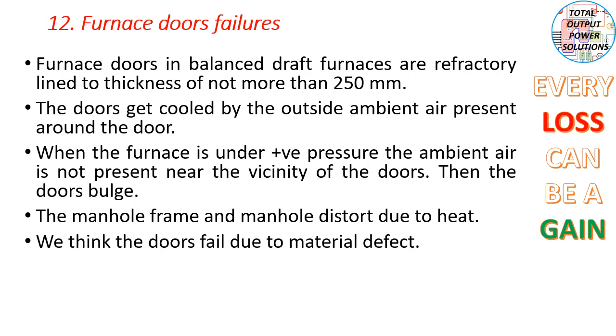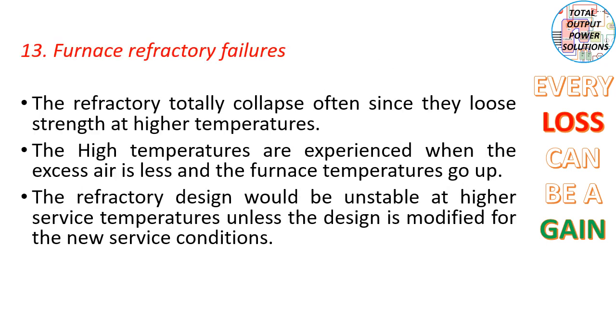Then furnace door failure. Furnace doors in balanced draft furnaces are refractory lined to a thickness of not more than 250 millimeters. The doors get cooled by the outside ambient air present around the door. When the furnace is under positive pressure, the ambient air is not present near the vicinity of the doors. Then the doors bulge. The manhole frame and manholes distort due to heat. We think the doors fail due to material defect.